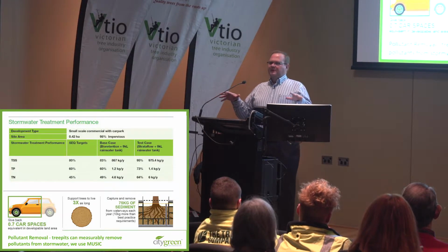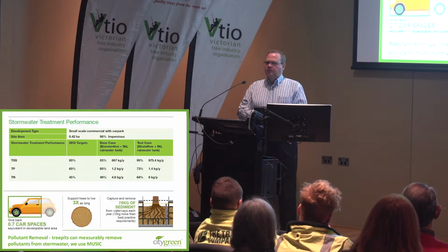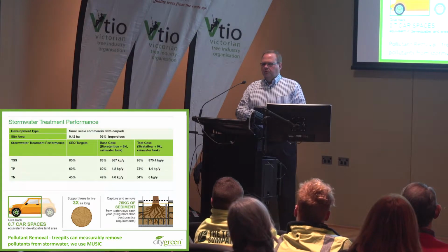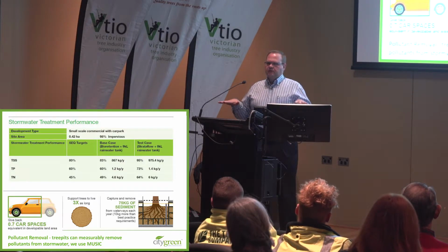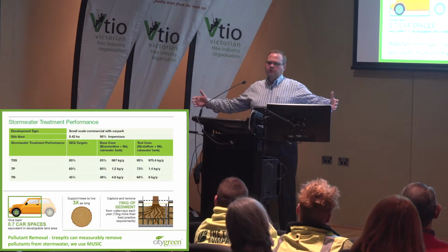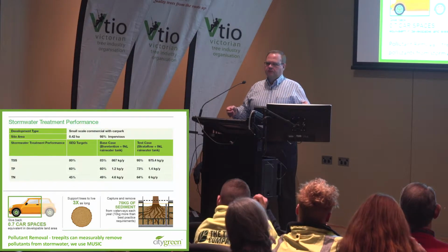So what we're doing essentially is taking the established science of bioretention and rain gardens, etc., and instead of trying to plant a tree in that, which, as you'd all know, doesn't work, to try and grow a tree in a soil media that's got a very high hydraulic conductivity, we're using loam soils, which has a slower infiltration rate, which means we need more of it, which plays right into our soil volume calculations.